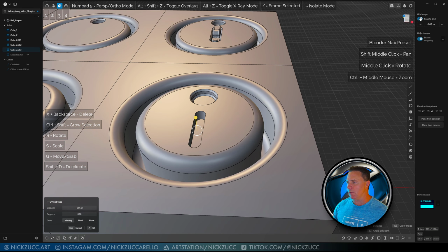Okay, like I was saying before, we can take these pieces. I'm just going to get rid of it, select it, tap 4, delete, like that. And then now I've got a chunk that I want to use to mirror across. So I can hit Alt-X, I'll tap F to do a freestyle, click on this like this. I can go whatever direction I want to go. I can go here, here, it doesn't really matter. So I'll click that and I'll tell it to merge halves together. Hit OK, like that. Okay, so now I've got that part and I can do this again.